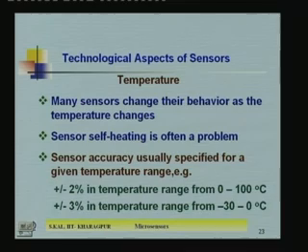Some sensors will work only if you apply some electrical power. So, if you apply electrical power to the sensor, automatically some current will flow through different components of that particular sensor. So, self heating is there. Because of the self heating, the parameter property may change also. So, these are the causes which change the sensor performance.